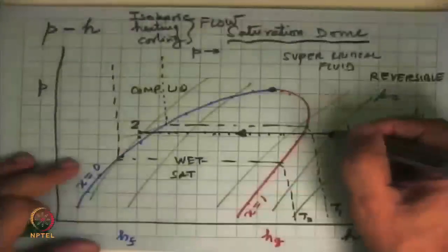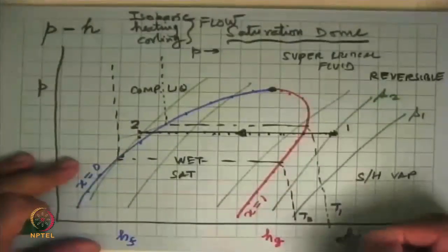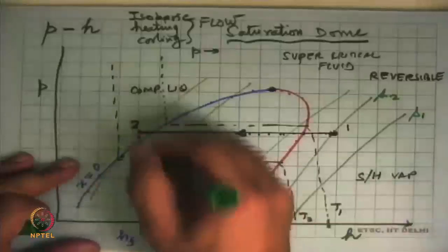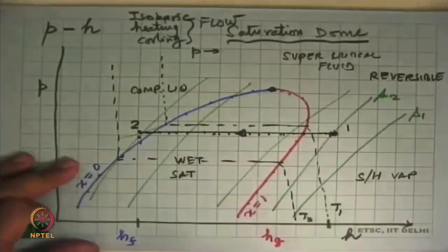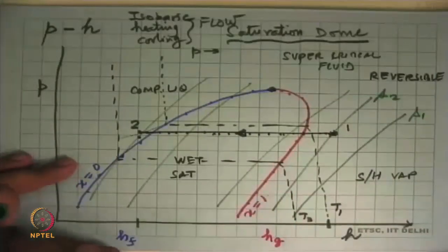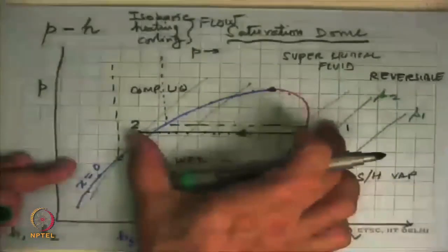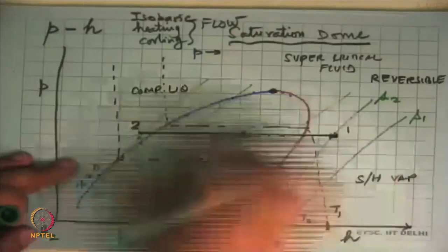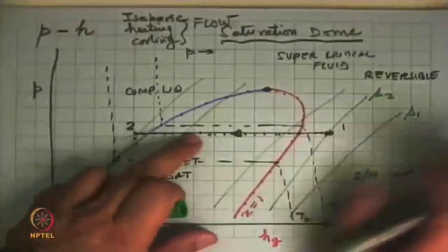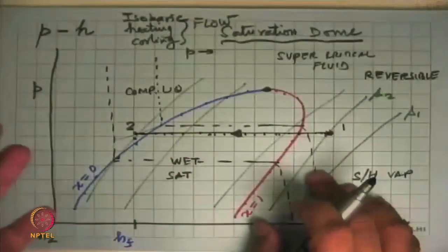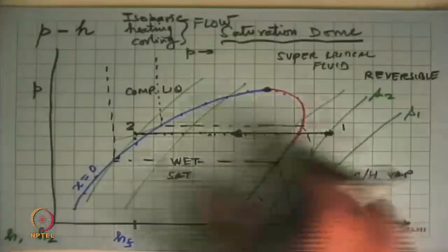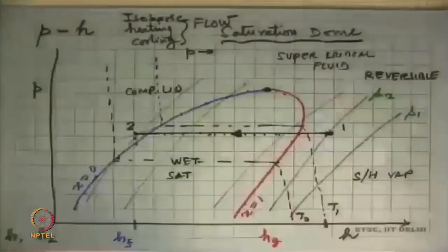That is quite nice because you can just go down this chart, look up this value of the specific enthalpy, go down this point, look up this value of the specific enthalpy. We can get H1, we can get H2, and the difference of this is the enthalpy drop during the process. That multiplied by the mass flow rate is the heat transfer in this process in steady state, no change in kinetic and potential assumptions. So that's a nice thing to know.